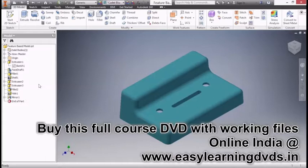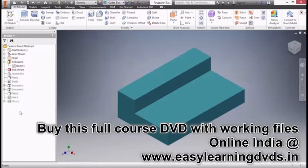Now, to better understand how this particular part was built, we're going to do a nice little trick inside of Autodesk Inventor called rewinding the history. So if I go here to the end of part marker at the bottom of this tree, I can click and hold on it and drag it back in time higher up the history tree. And what will happen is where I drop it, let's say right here above face draft, it takes me back in time to when that feature was created and before anything else was created after it. So this is your little time machine. So you can drag this up and down through your history tree to examine how something was developed.